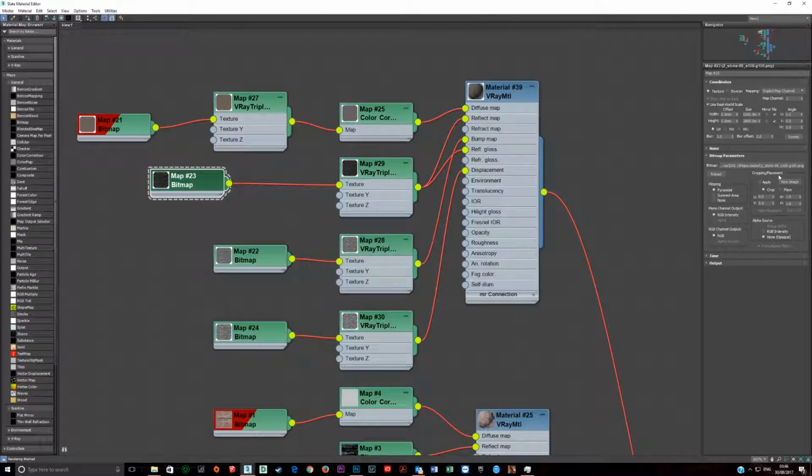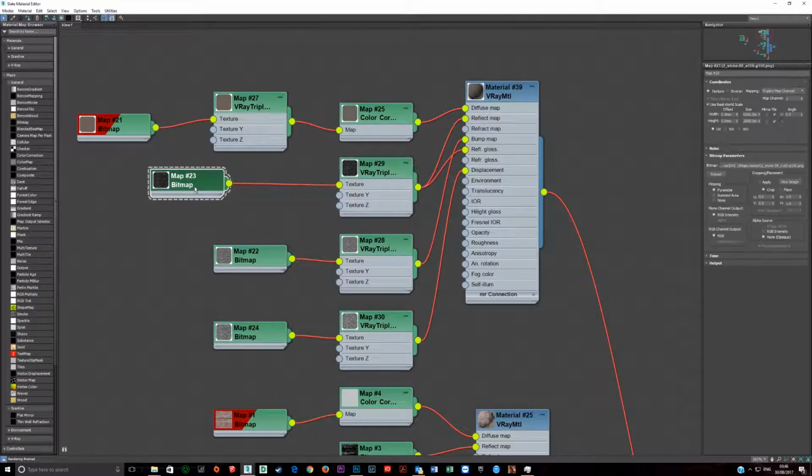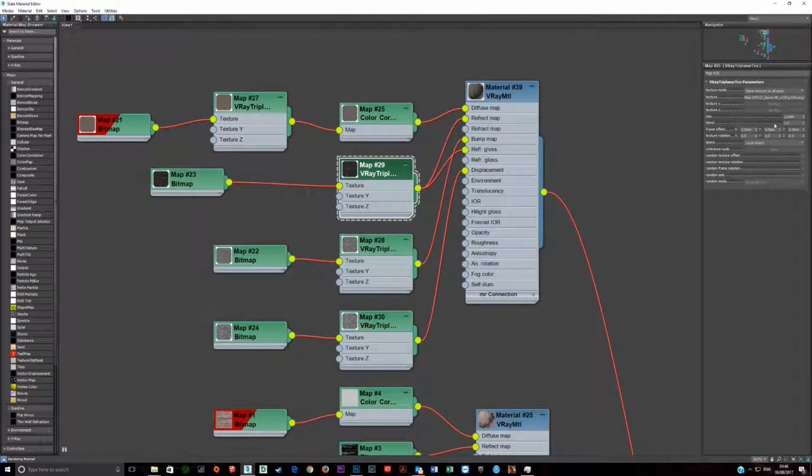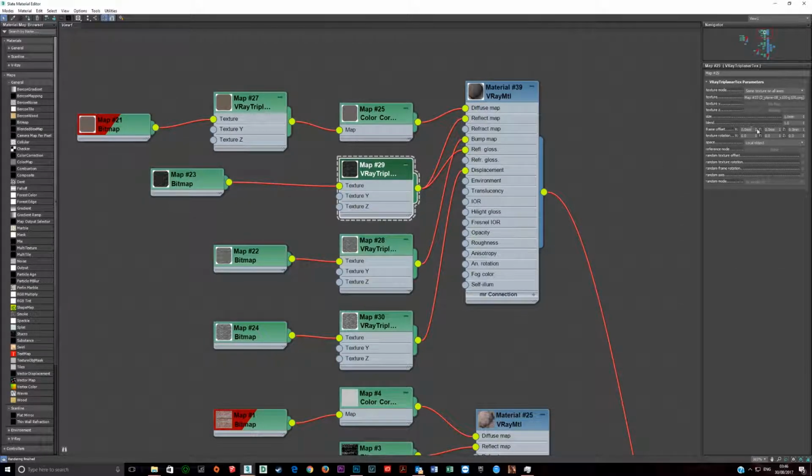So this bitmap comes in, and it's set to use real world scale. And this, I've got this set to size 1 mil and blend 1. So this in essence is telling it to just use Y1. It's saying use this one. Don't look here for the size. Look here. So it's looking here and using this size. So that's what the 1 is.